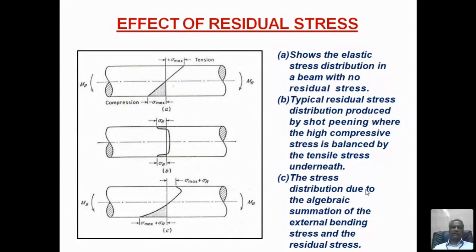Okay, this is the criteria you have to meet when you do the welding. If all the curves fall below the IIW guidelines or IIW fatigue curve, then the joints you cannot apply in the actual applications. Okay, so to compare that, you have to use this graph. And this is for notch specimen. So from these two SN curves, one is for...